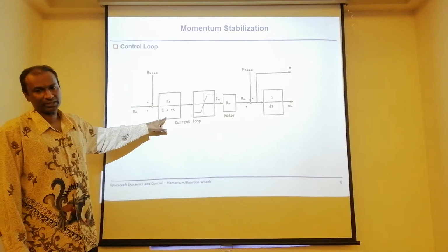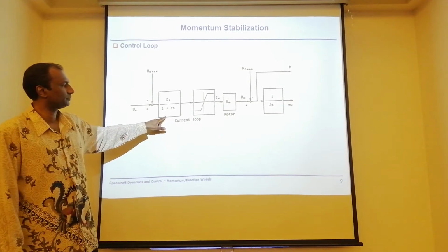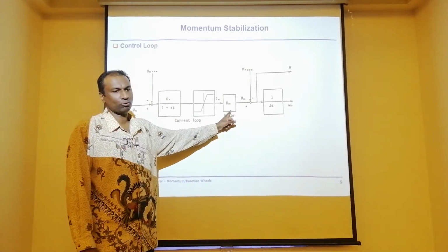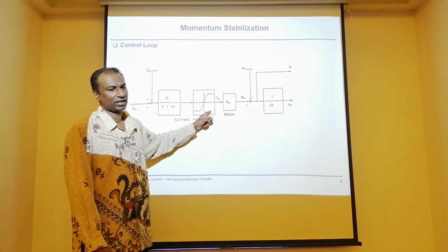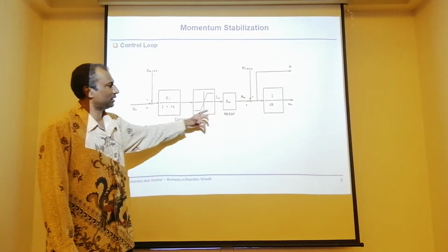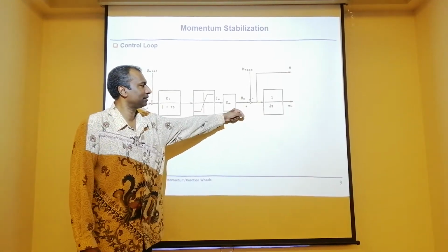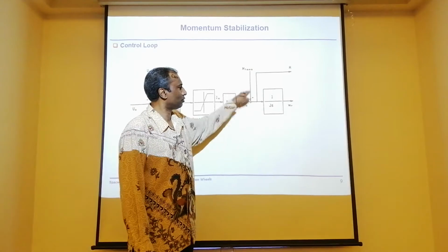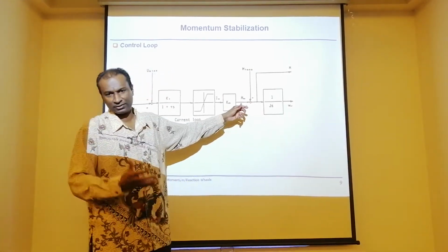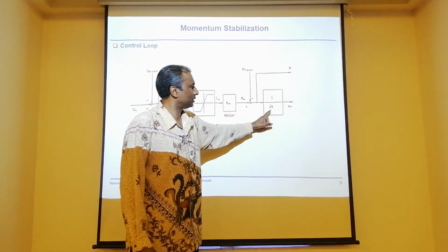Typical, basically, first order. Just a proportional controller. You have current, and this is basically the motor constant that you have. So how much current? This is a typical motor controller. Just to tell you, how much current you inject is the amount of torque that will be generated. Then you have some sort of losses of the wheel, the eddy current loss, all those, so quite typical. Then it goes back to the actual wheel.